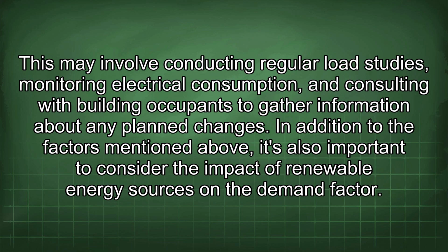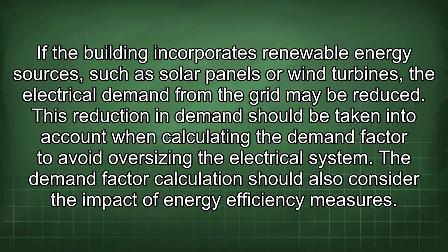In addition to the factors mentioned above, it's also important to consider the impact of renewable energy sources on the demand factor. If the building incorporates renewable energy sources, such as solar panels or wind turbines, the electrical demand from the grid may be reduced. This reduction in demand should be taken into account when calculating the demand factor to avoid oversizing the electrical system.